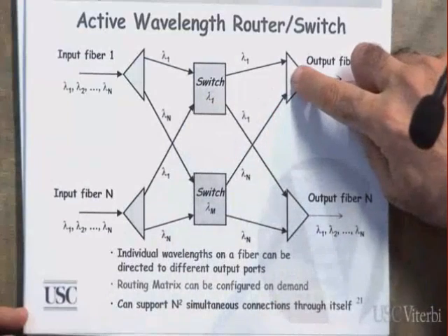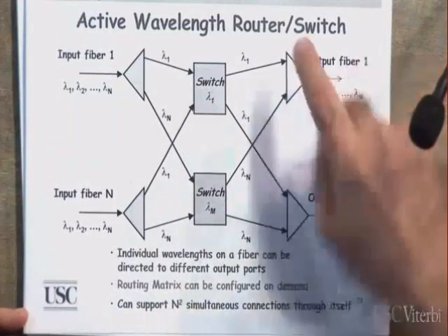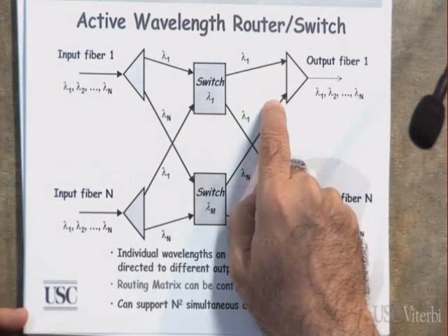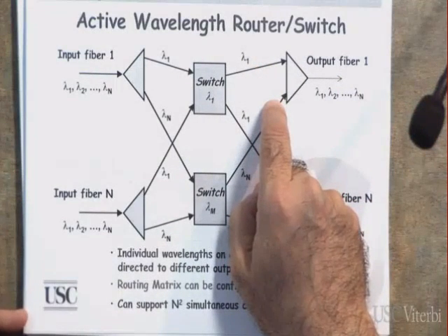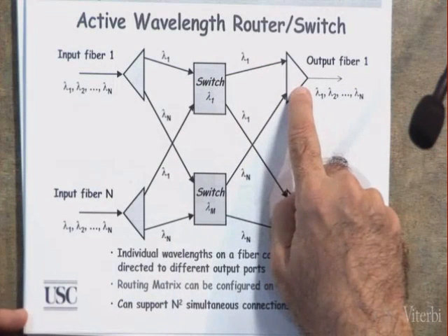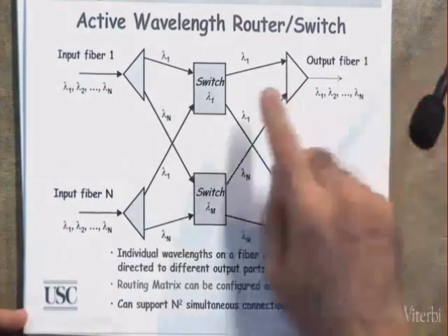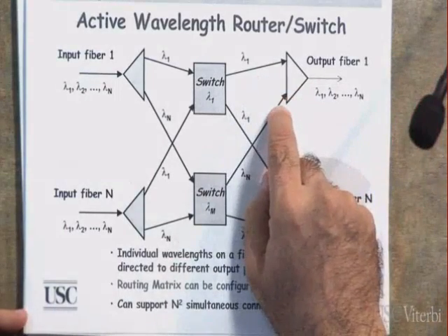When it comes to here, listen to me. Those inputs, could they be of the same wavelength? They cannot be of the same wavelength. Why? Because this one is going to combine them, to multiplex them. Are you following me or not? You cannot have the same wavelength here.